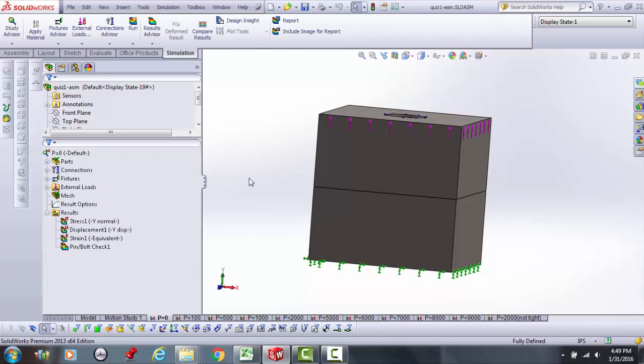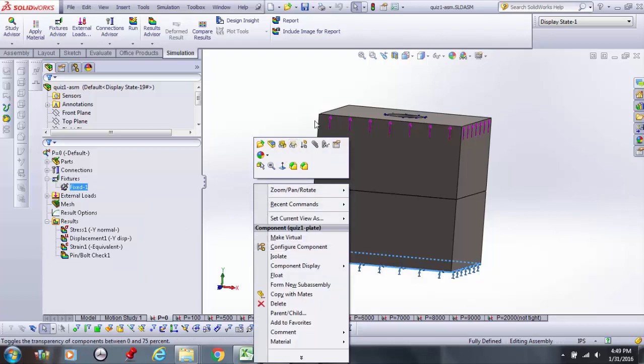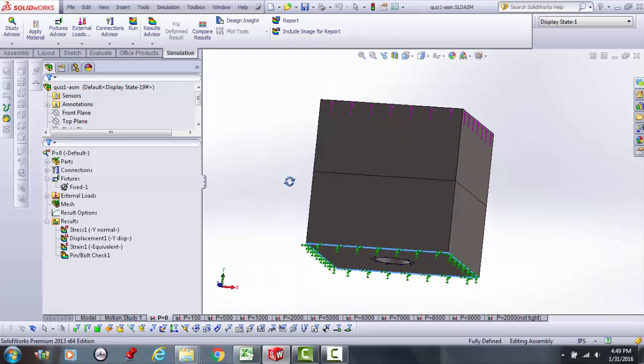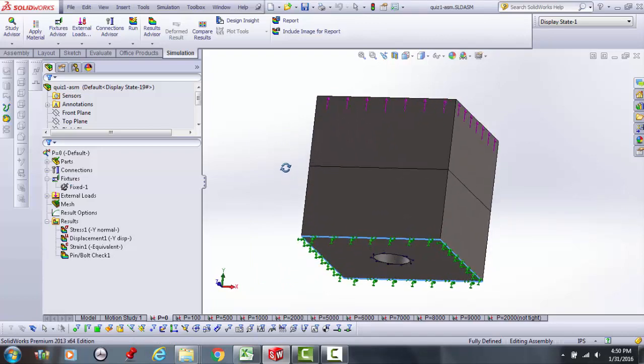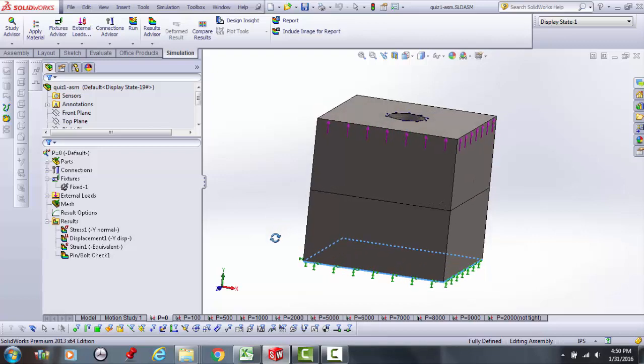And in an assembly, of course, you are still worried about how you anchor. And what I did is I anchored the bottom edge of the bottom plate. Anchoring is important. And here I tried to avoid the hole of the nut, so I actually fixed the outer edge.